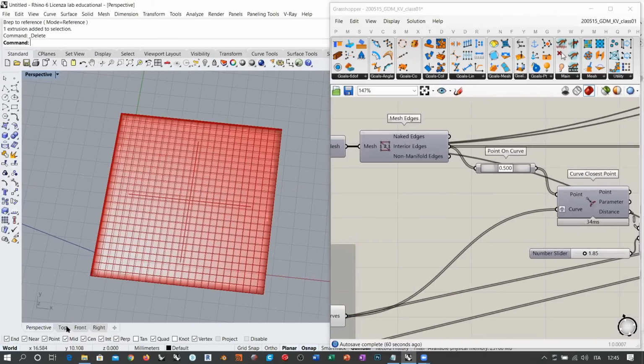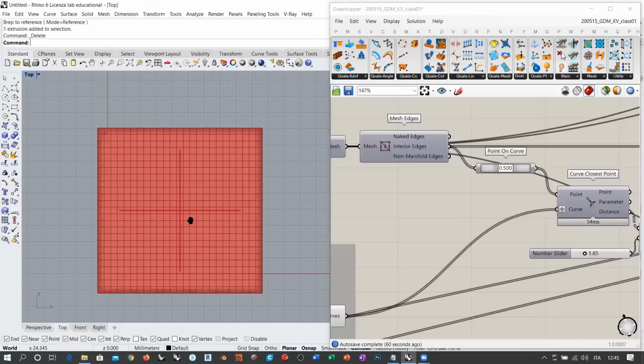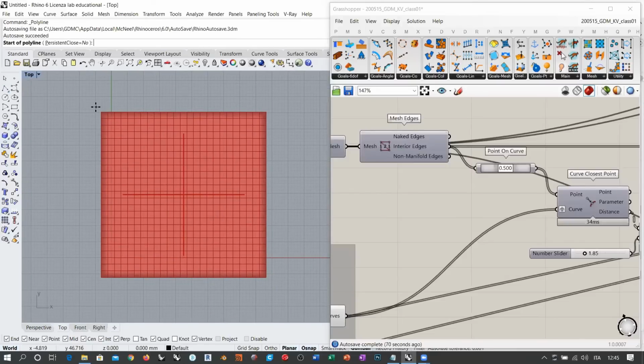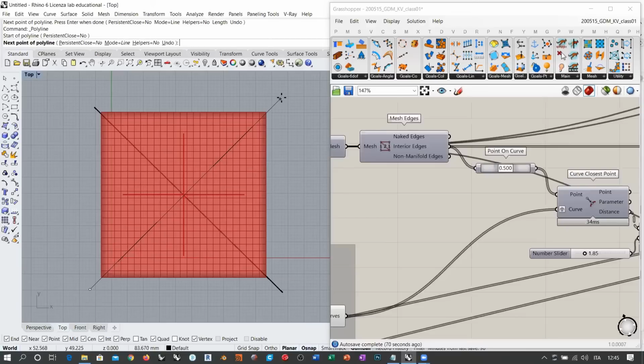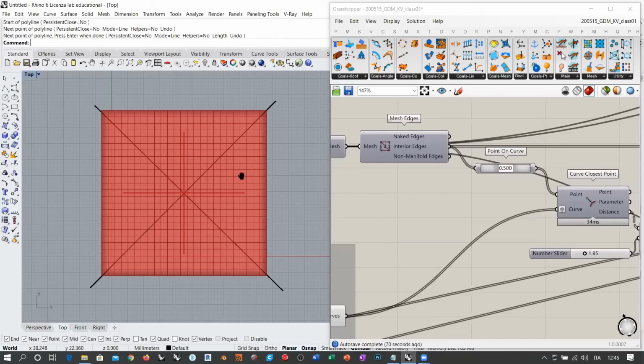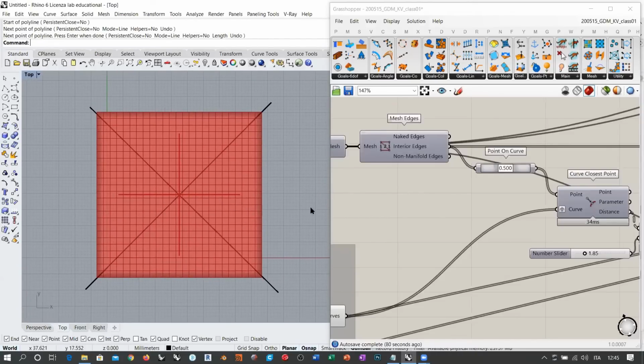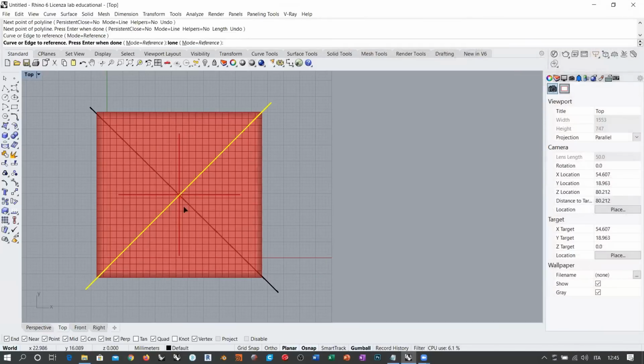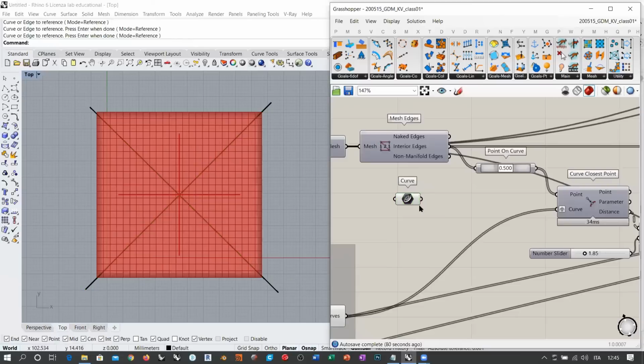And what I'm going to use, I'm going into Rhino, and I'm going to use this line here and this line here. A little imprecise, but it will work. So I'm going to take curve, set multiple curves, 1 and 2. I have 2 lines here, and I'm going to use them grafted, of course, like here.